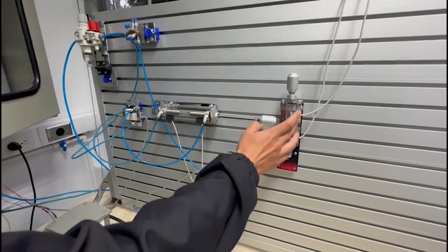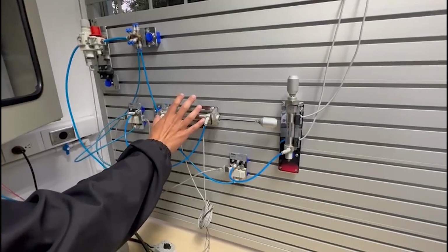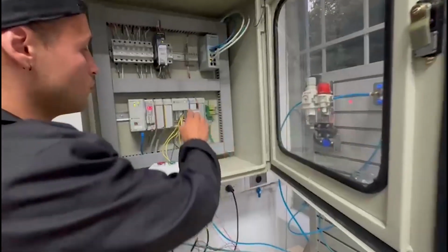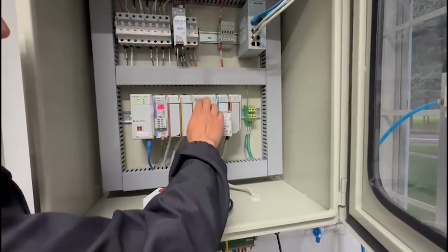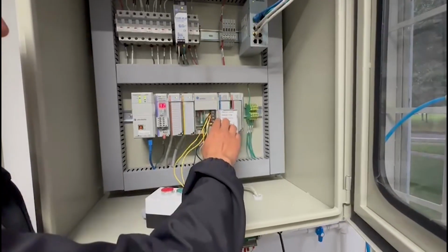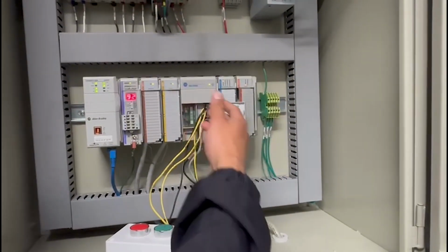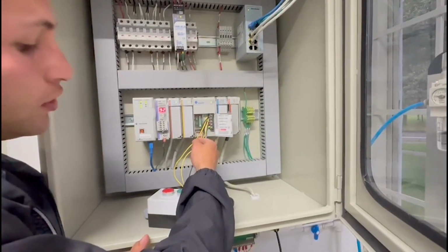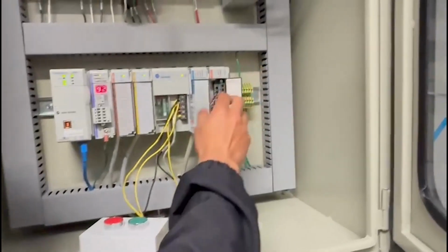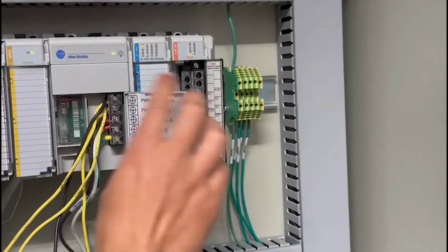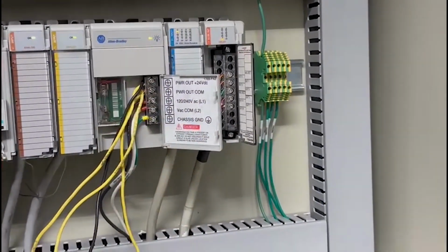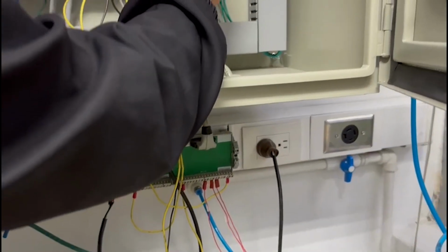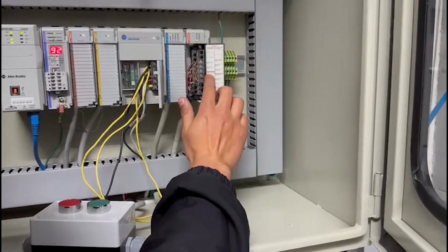So for this we first have to supply energy to the relays of the electropneumatic elements. There are three relays, and we have the source from the PLC from Allen-Bradley, which has a converter that gives you the option to get 24 VDC. Then we have to connect this 24 VDC to our digital output relay. So we get the power here, take it out, and connect it to the digital input of the relays for the power.